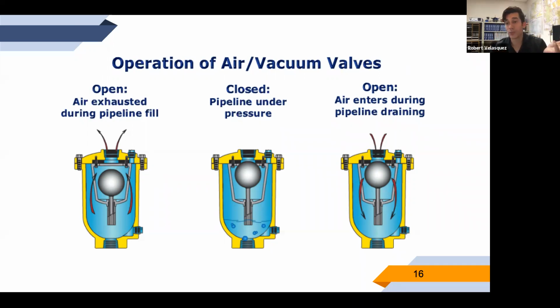This is also really similar to what we have in a car with your gas tank and your gas gauge, or gas dial. I'm going to remember what it's called later, but you have a ball basically in your gas tank that's floating up, and you're reading how high that ball is to determine how much gas you have. That's why you always have a little extra gas before your gas gauge starts to go down: the ball can only go so high, and the gas level will go all the way to the top. It takes a little while for that gas level to drop before the ball will start to drop.